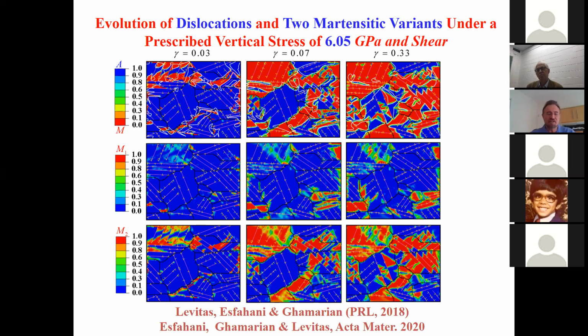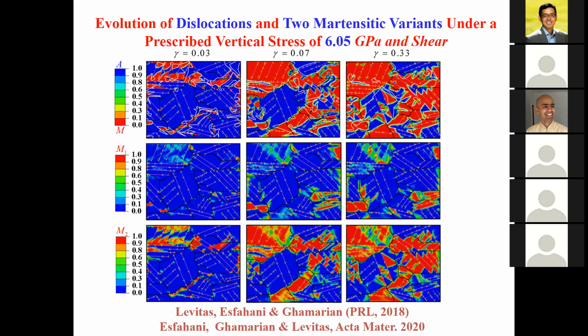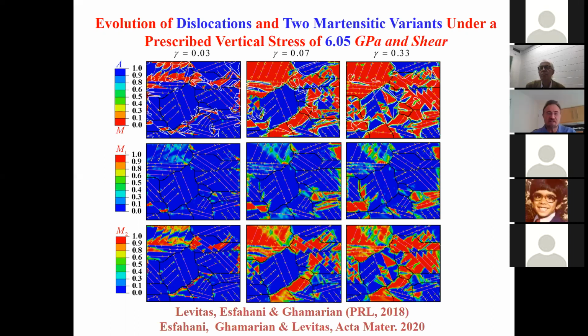Okay, general answer. If you are above recrystallization temperature, then the effect cannot accumulate. You cannot produce dislocation pileup or any strong stress concentrator. The material will recrystallize and annihilate them. So in the limit case, if you are above recrystallization temperature, this method will not work. At lower temperature, it depends on many parameters. It depends whether temperature itself promotes phase transition or suppresses phase transition.